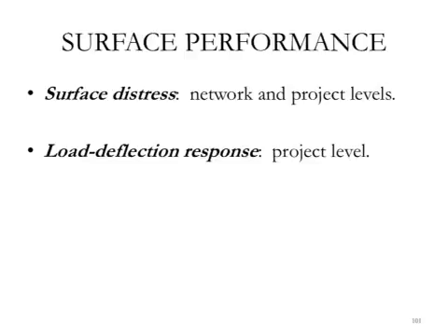So when it comes to surface performance, we will be talking about surface distresses, which are typically covered at both network and project levels. When it comes to load deflection response, it is going to be mainly for project level. So to summarize, we have two surface performance measures: one is the distresses and one is the load deflection response. Typically, project level, as we talked about before, would be interested in measuring more information about a certain project, and that's why we will be talking about load deflection response besides the surface distresses.